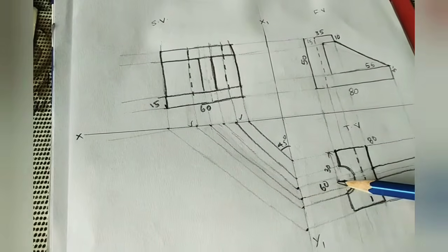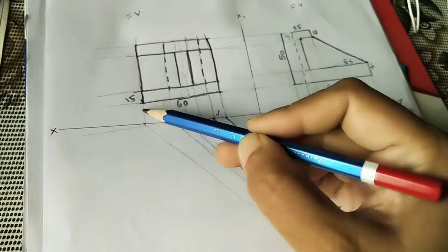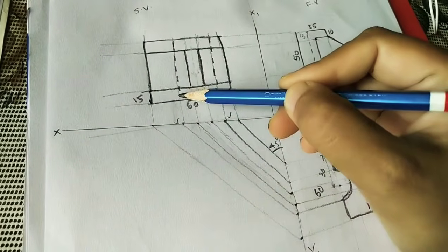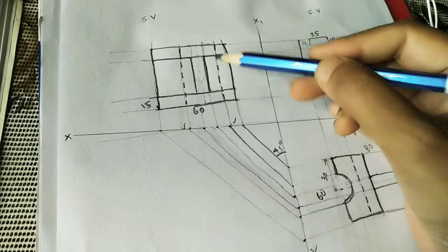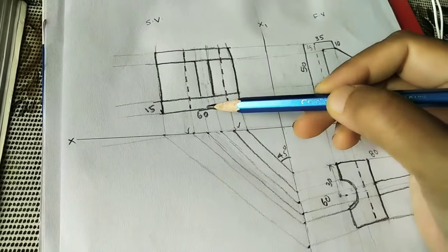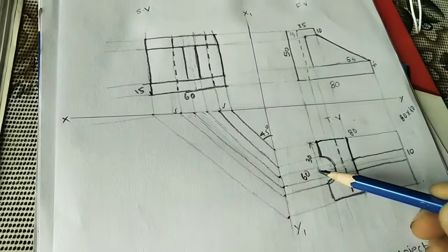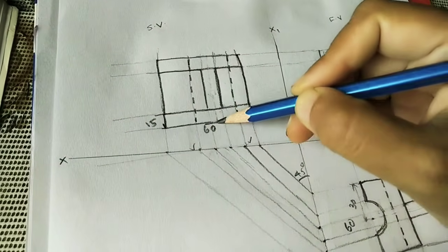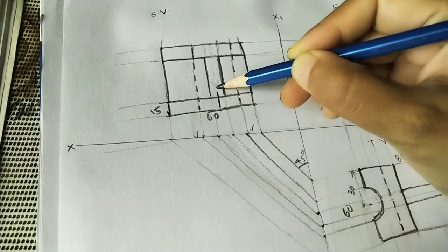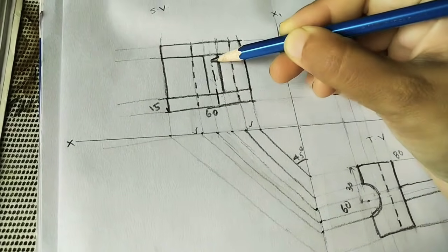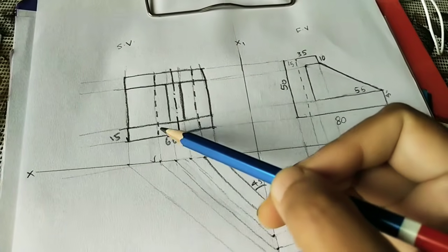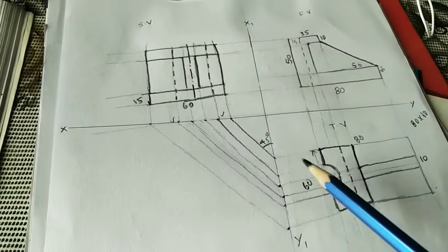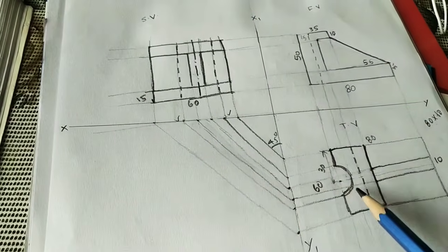At the center also, the center line we didn't do. Here do the center, or in 60 mm take the middle point. Okay, so this is the entire length. Just continue this up to the entire height, and at the center do the axis line. Axis line means it is an imaginary line passing through the center. So at the center of this 60 mm, do the axis line: two long lines with a dot. By seeing the axis we can say it is a circular hidden part. Okay, if the axis is not there, we can assume by seeing this that it has a rectangular hole.